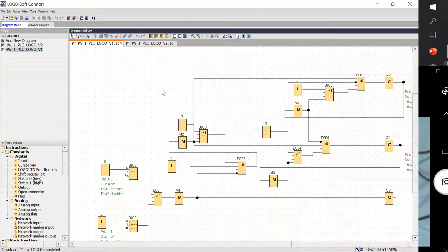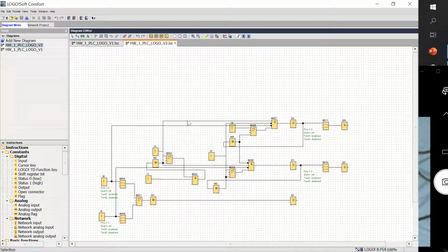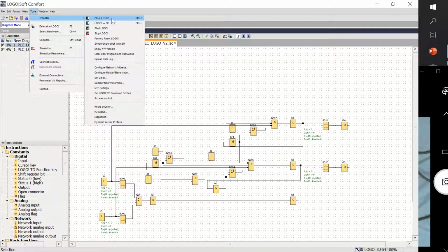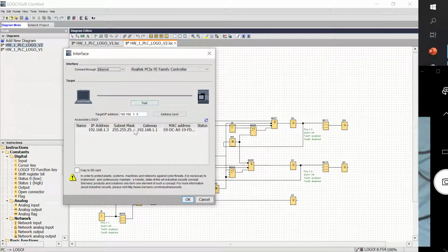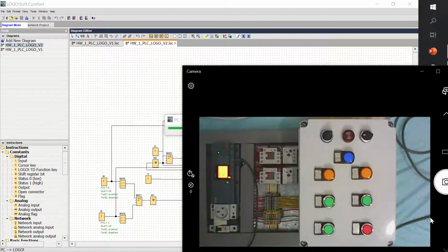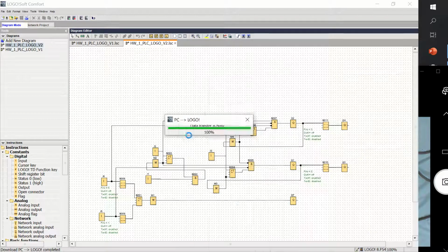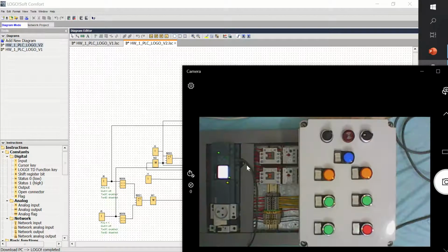Now, using version 2 of the solution, we have embedded the needed modifications, which are not that difficult. We can follow the same procedure and download this version to the PLC. We test the connection, put it into stop mode, and notice the transfer. Now we can hit yes, so that the PLC is ready to operate, and we can also try the operation.